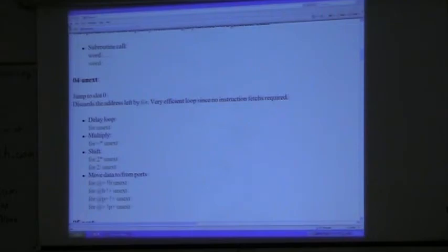This incrementing fetch, the increment is suppressed if A was pointing at a port. So this would be suitable for going from one port to another port. Now here's the converse of that: fetch from B and incrementing store to what A is pointing at. I'm sure there's a difference between them. You use the one that works for you. We might have some of these in ROM for no good reason. It's only one word.